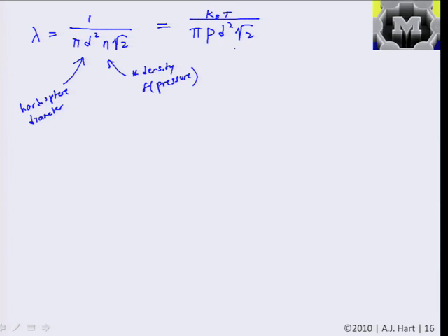So if the gas expands, the mean free path gets bigger. If the pressure goes up, then the gas is compressed, and the mean free path goes down, so the molecules travel a bit less than before they collide with another one. And remember, we defined on our chart before that if the Knudsen number is, say, less than 0.01, we say we're in the regime of continuum or no slip flow.